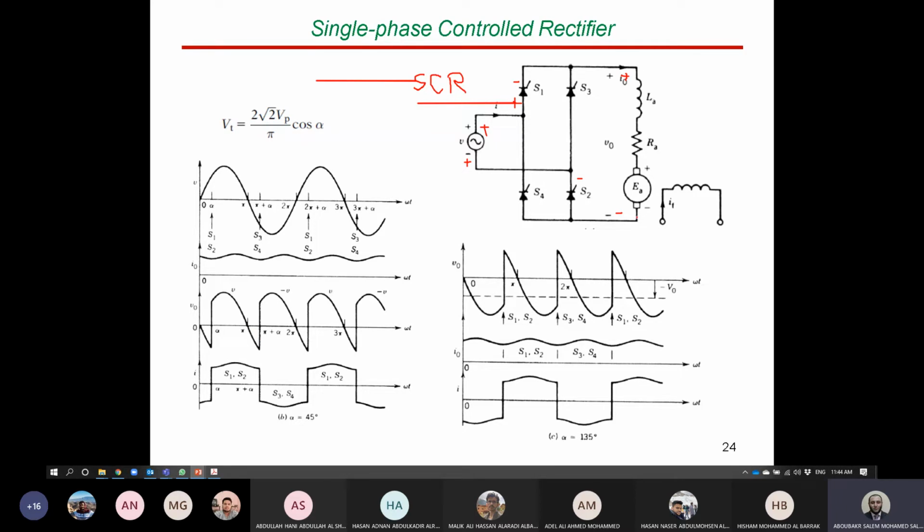Like we said, we need a DC source. Is the negative value of volt here effective, or will it affect the motor performance or not? If it will affect the motor performance, you know, for a motor we have our torque-speed characteristics, this is omega and this is torque, the motor characteristic or the operation of the motor. Omega will be positive if voltage is positive. Torque will be positive if current is positive.